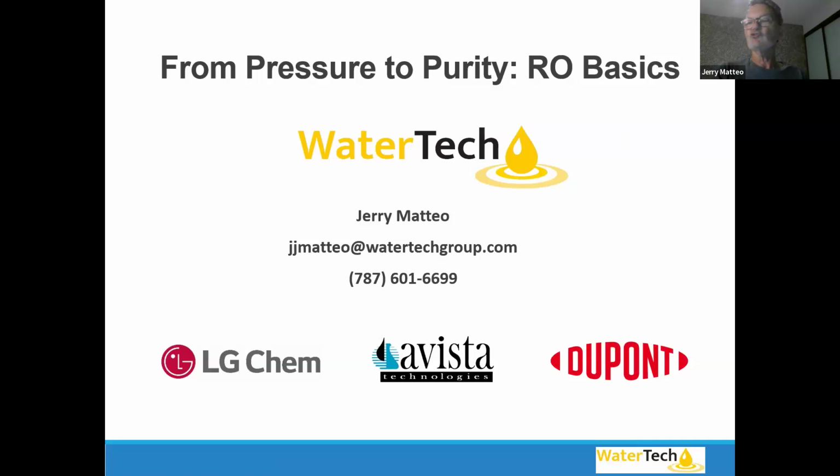And so your membrane, I hope it came through, we only want the membrane to remove or reject dissolved solids. It's going to plug with all that other stuff. Oil is going to plug it right away. Turbidity, particles, are going to plug it right away. Bacteria will also grow a biofilm in there, which I didn't talk about in this presentation, and we don't want that.